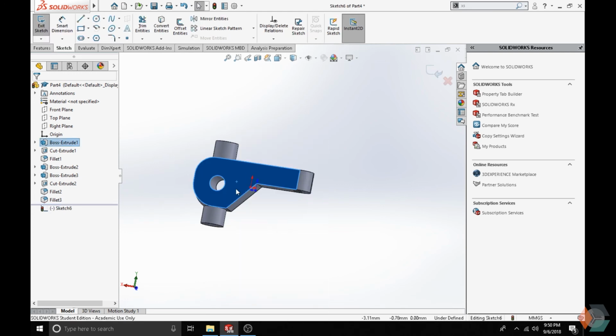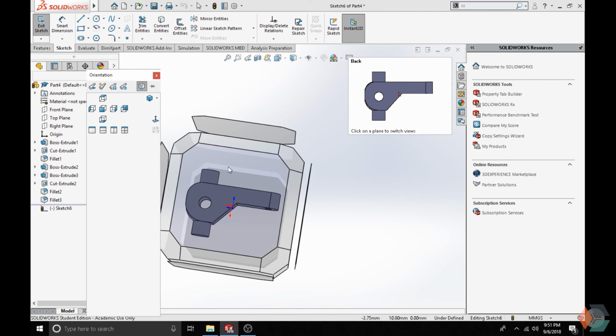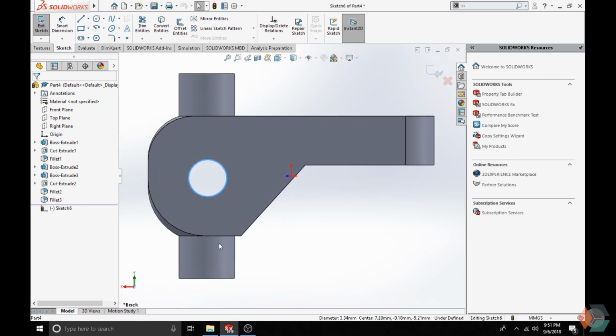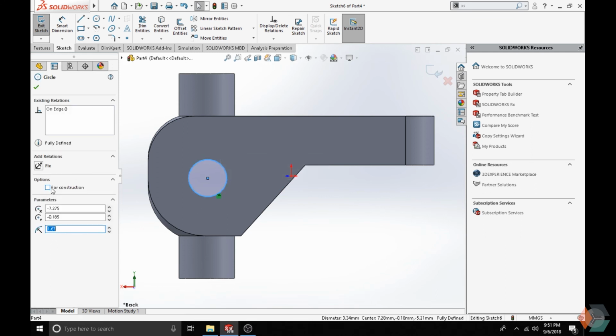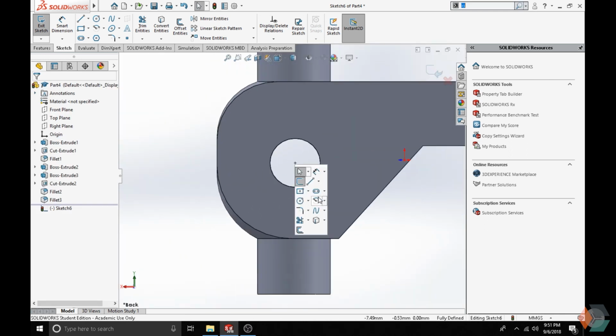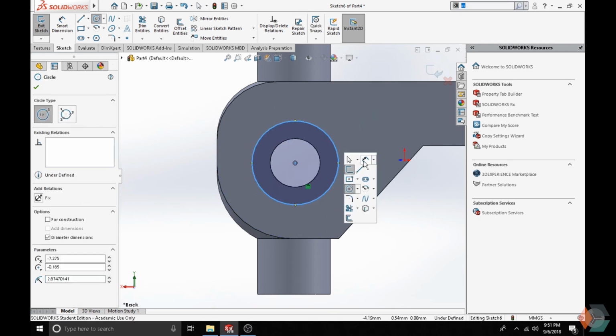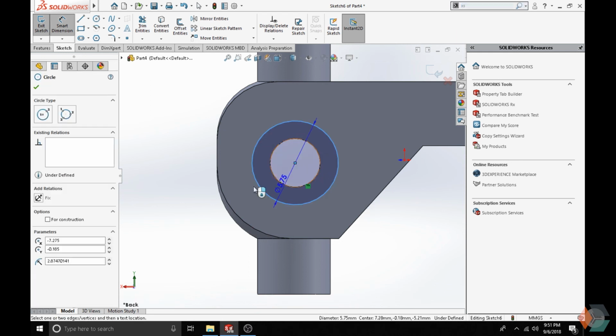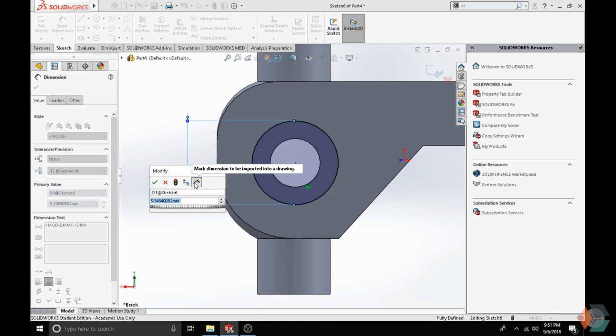Need to cut with a circle. So hit the space key. Select the inner circle. Convert it to an entity, which is a line. Select that circle, solid line, and change it to a construction line under option. Confirm the option. Zoom in at a construction line. Now, select S and draw a circle on it. Change the diameter to be 8 millimeter.